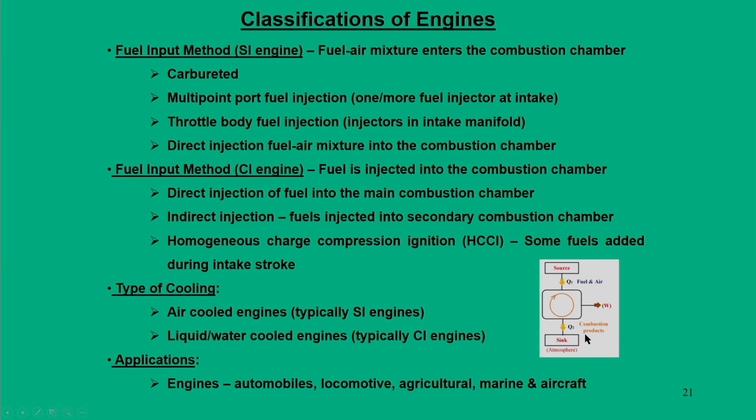The engine gets hotter and hotter as it operates. So, based on that, we can have air cooled engines, typically SI engines, where the engine is cooled by means of circulating air. The other option is liquid or water cooled engines, using water jackets. That is mainly used for CI engines.